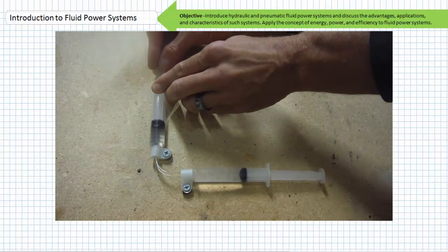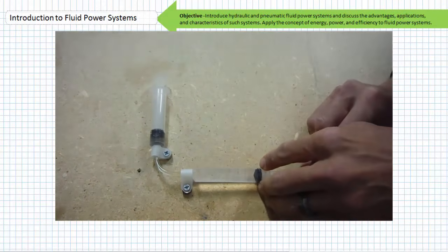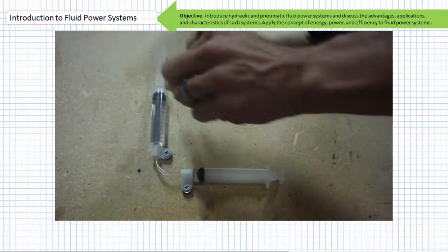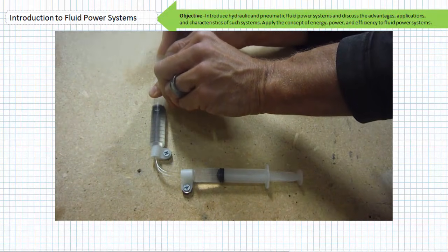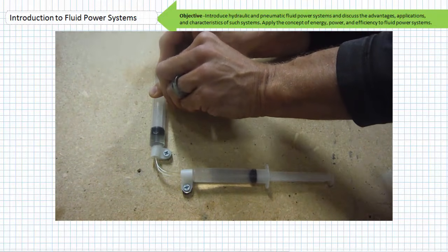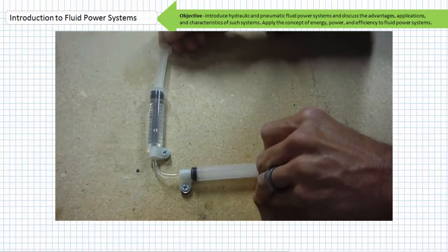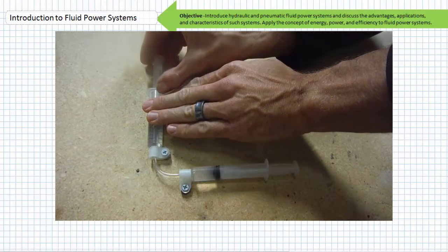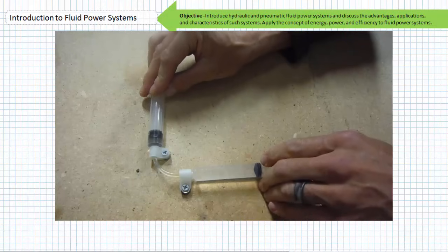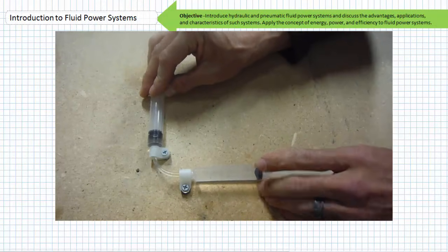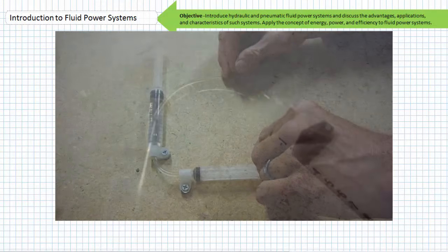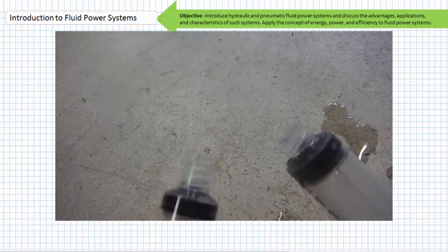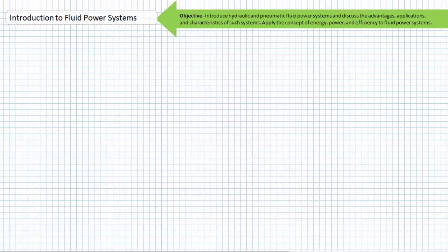In contrast to our previously examined simple pneumatic system, note the consistency, predictability, and regularity with which the hydraulically driven actuators extend. There's no lag in actuation. Additionally, note the firmness of a hydraulic actuator supporting a load. These observed characteristics are due to the incompressible nature of liquid and present a major advantage over pneumatic systems. In the interest of fairness, when a pneumatic system springs a leak, it's far easier to clean up than a leak in a hydraulic system.